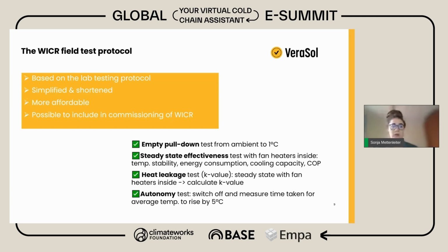So that's why we say a field test is necessary too, to actually still test whether your cold room does what the spec sheet says it should do. And therefore, we would also recommend to include such a field test in your commissioning, because that way, as you get your cold room, you can really see, does it do what it's supposed to do? And it consists of the empty pull down test, the steady state effectiveness test, the heat leakage test, and the autonomy test. Sometimes people ask, why is it necessary?